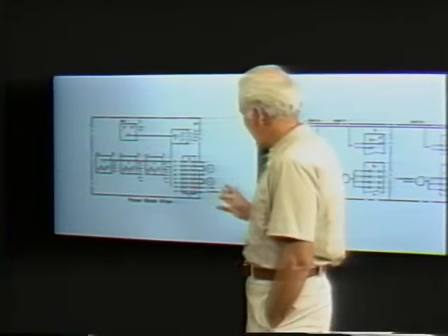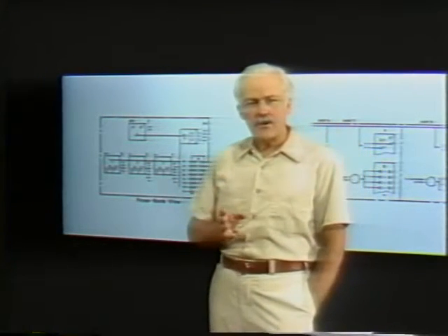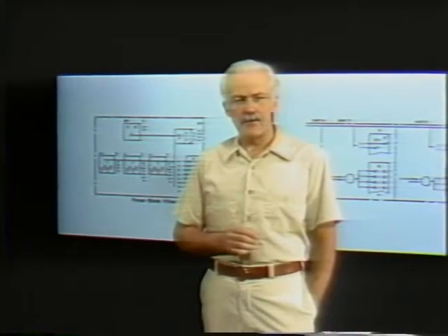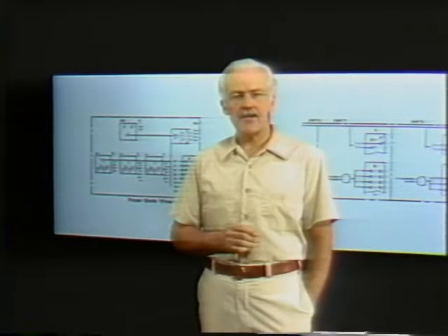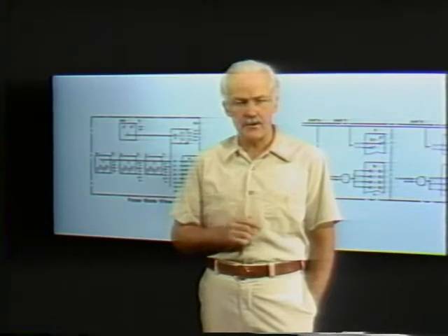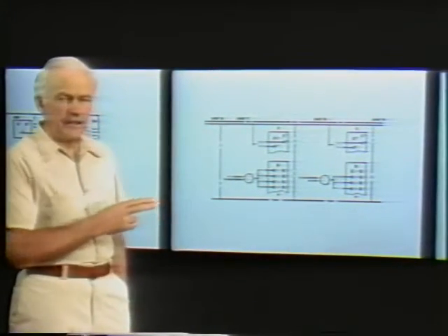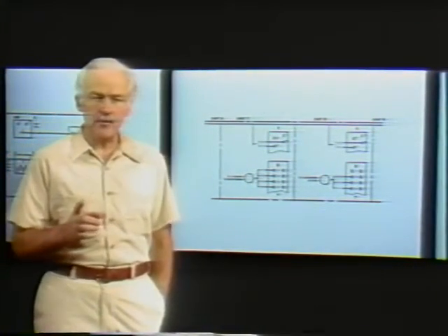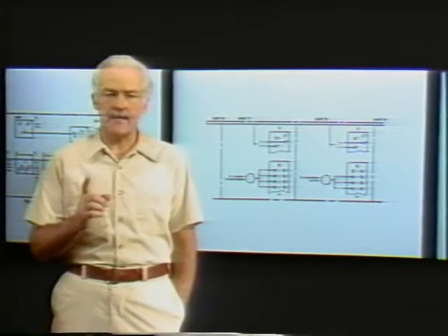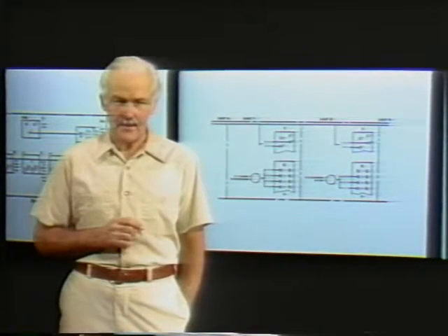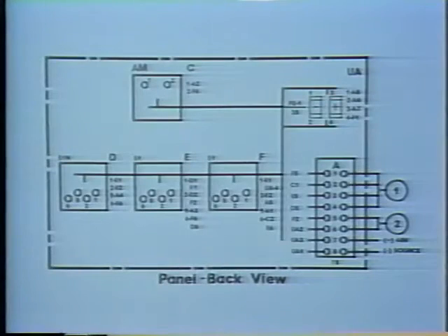A connection diagram is a drawing showing the general physical location of all major components and the connection points of all wires within a single unit. An interconnection diagram is a drawing showing the wire connection points between different units that are electrically connected together. First, let's talk about connection diagrams. Connection diagrams are a tool that the manufacturer usually uses. However, if connection diagrams are used properly, they can be of value to you as a maintenance person in your work.